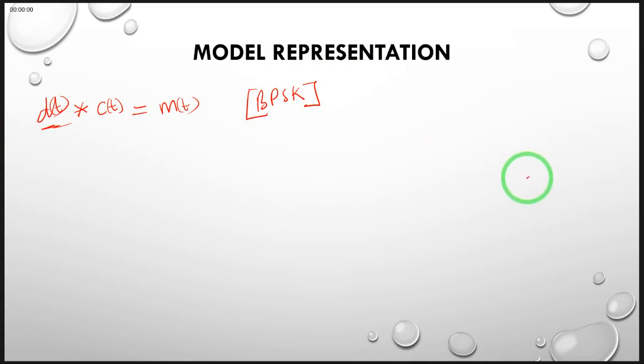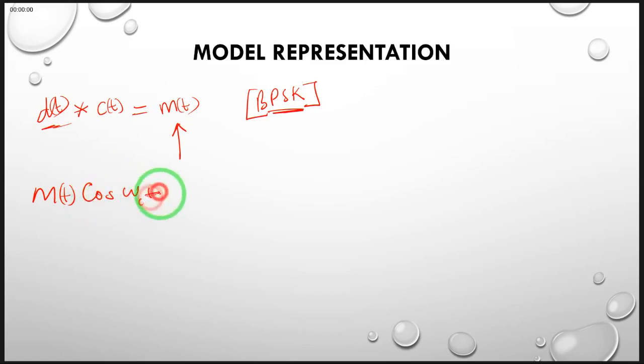of the demodulator. So assuming we are sending m(t), this is the easy part, because even if we do not ignore the BPSK bit, m(t), when it goes through the BPSK modulator, will be multiplied with the high frequency carrier cos(ωc t), and this is what is transmitted through the channel. At the receiver, we employ coherent detection that has a local carrier synchronized with the one that was used at the transmitter.